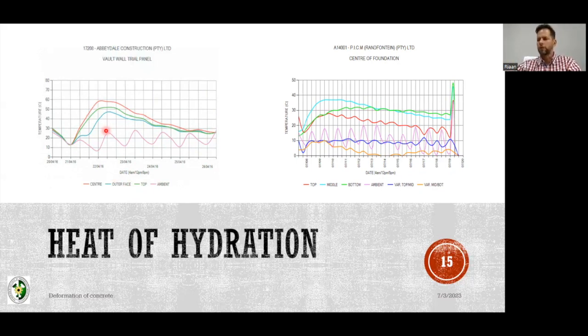And then we were able to determine from this that you need to wait 1, 2, 3, 4, almost 5 days before you remove those shutters. Those shutters will be a cooler box or a jersey or a jacket that this concrete is wearing for that time period until your temperature differentials settle out and you do not jump above the 20 degrees. Then you are ensured that you will have a good temperature range.